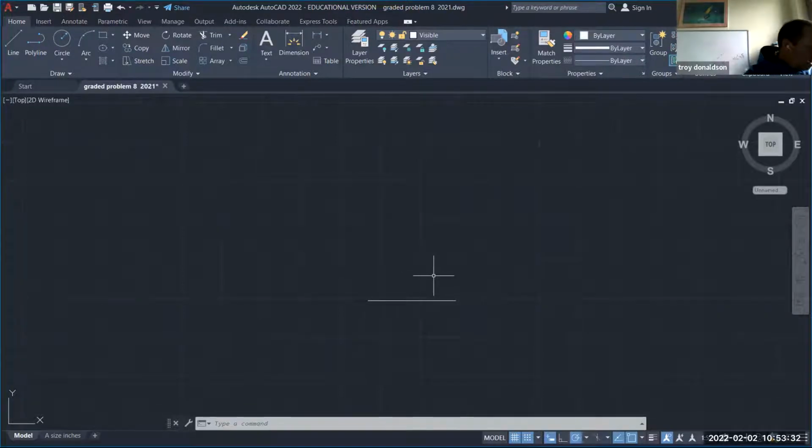So I went 5.5 across, and now I'm going to go up the 0.62. So hooking up with my object snaps, and I'm just aiming and shooting, right? 0.62. And I'll just bring it all the way across. And hopefully you've noticed that you can drag points. So see how the green line is going? That's going to keep it horizontal.